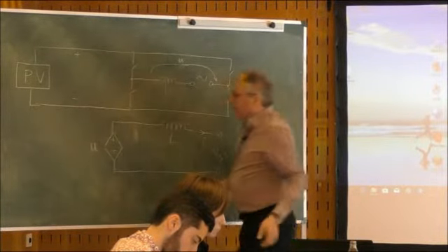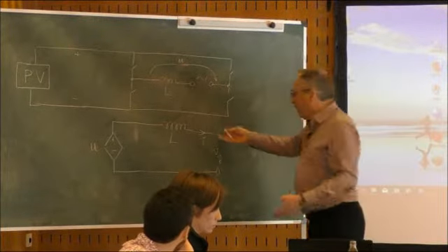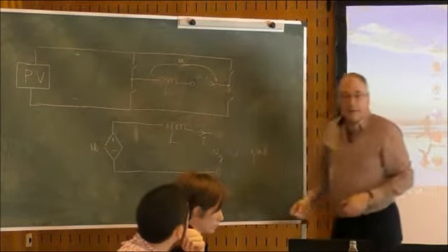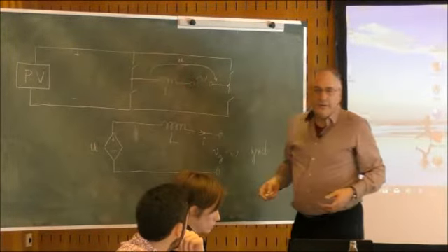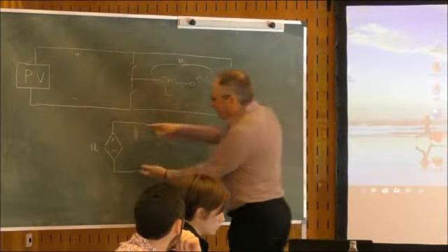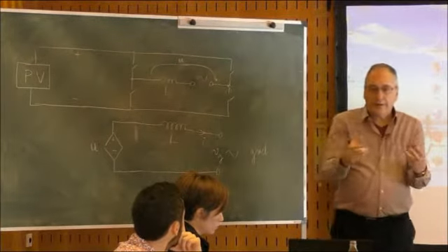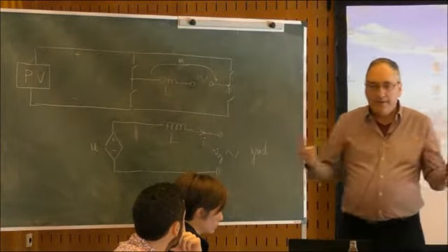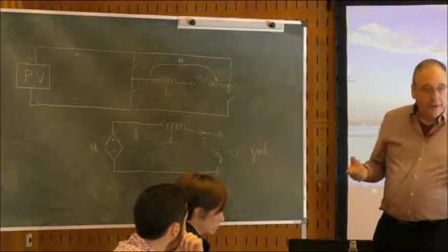Okay, and this voltage is now applied to the inductor, and through the inductor it goes to the grid. You understand that there must be an inductor here. If you are an engineer, you understand, because I cannot connect a voltage source to another voltage source. You cannot connect together two voltage sources, because then any difference between the voltages will create an infinite current.